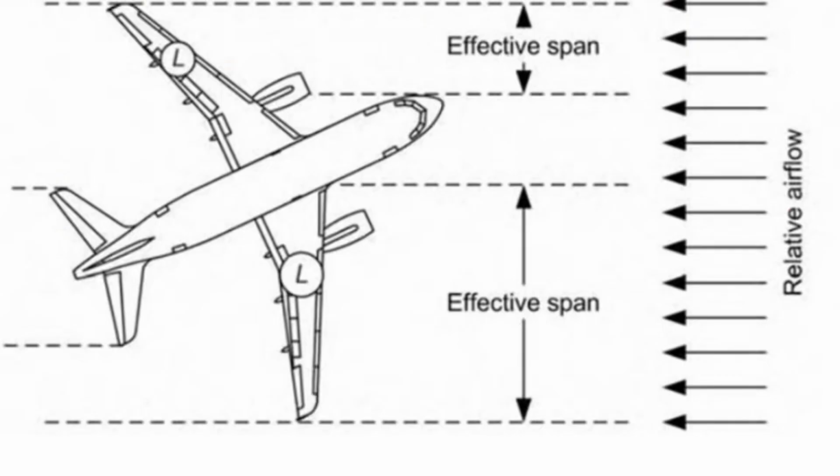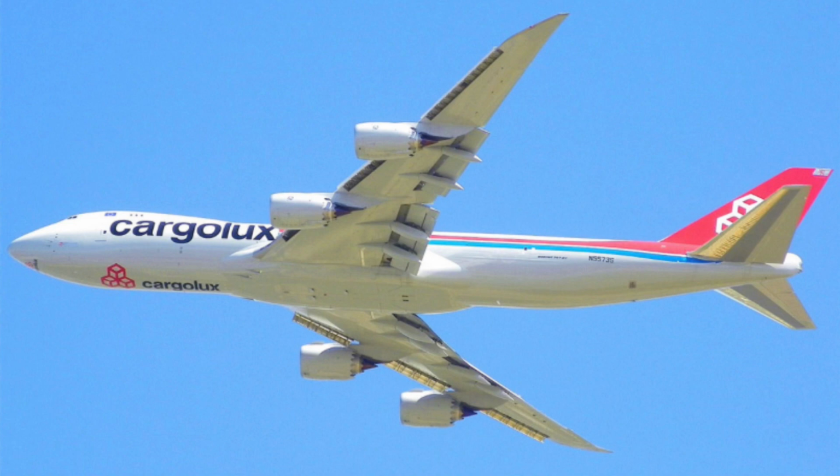Now let's talk about swept-back angles. Swept-back is an angle at which the wings are slanted rearward from the root tip. When a swept wing airplane is side slipping, the wing toward the side slip will experience a greater volume of airflow over the lower wing than on the wing away from the side slip. This will allow the lower wing to increase lift and return the plane to straight and level flight.